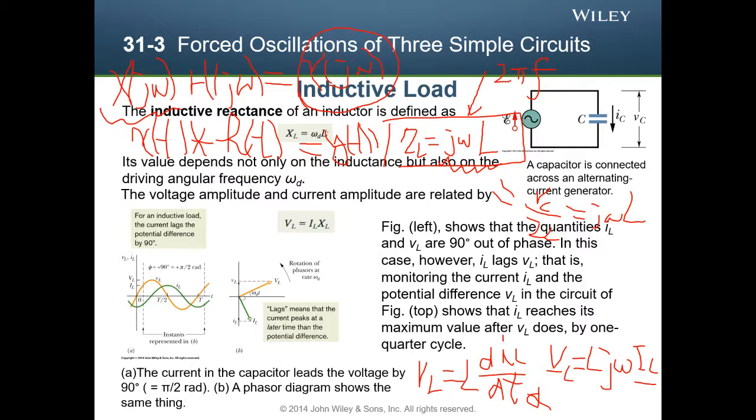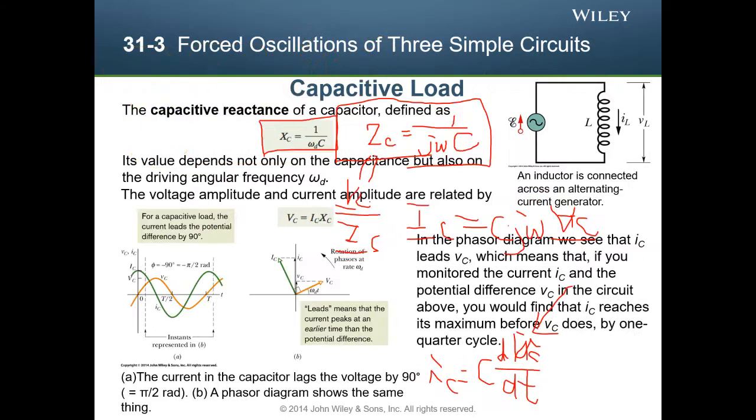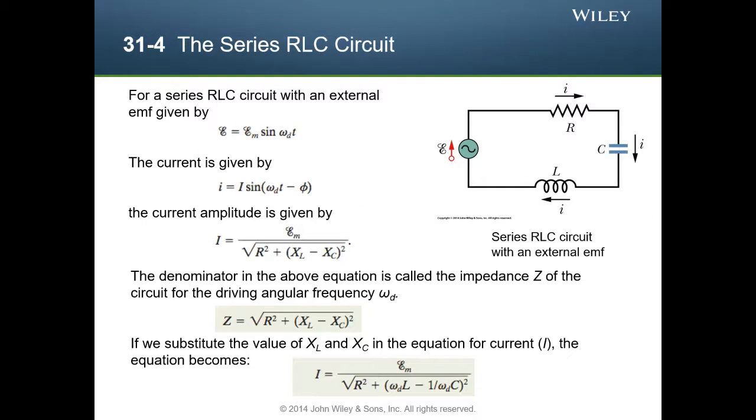You only need to calculate the Fourier transform of them, multiply them together, and then you get the Fourier transform of the output signal, and then you take the inverse Fourier transform, and you can get the output signal in the time domain. You don't really need to calculate the convolution. So I think, yeah, you will calculate something like that.